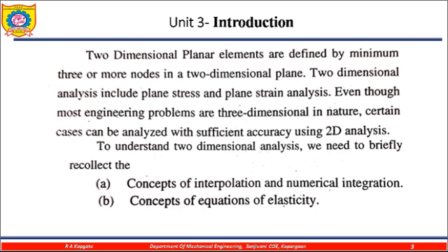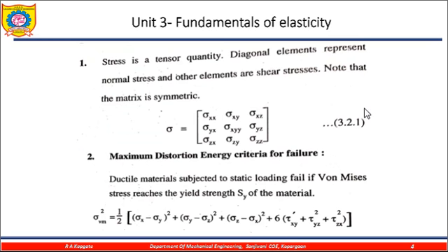Now, stress. What is stress? We still do not understand stress in the right way. We consider stress by a very simple formula, that is force upon cross-sectional area. But actually stress is a tensor quantity, and when we define stress in terms of 3 dimensions, we need to write stress in the format of a matrix: sigma xx, that is along the x-axis, then sigma yy along the y-axis. Here there is no x, this should not be written here.